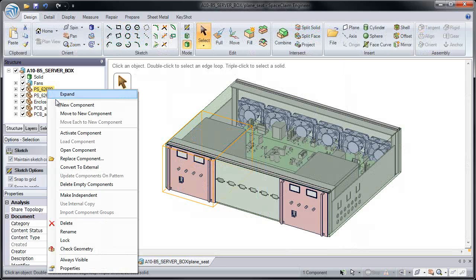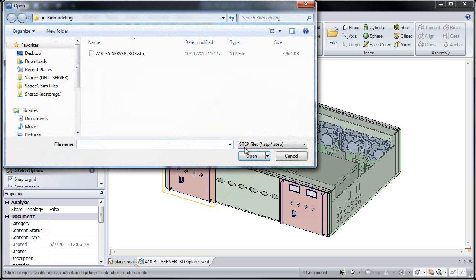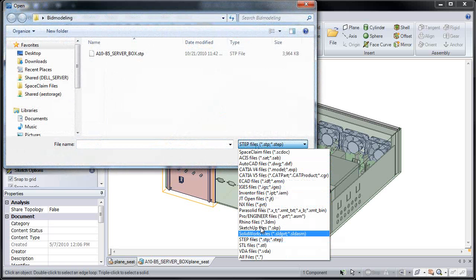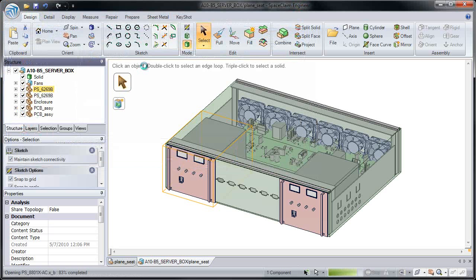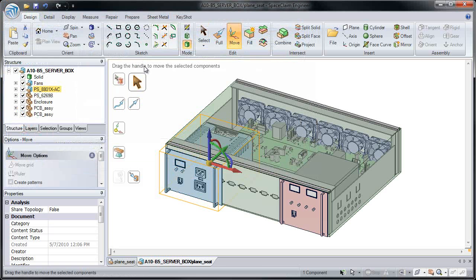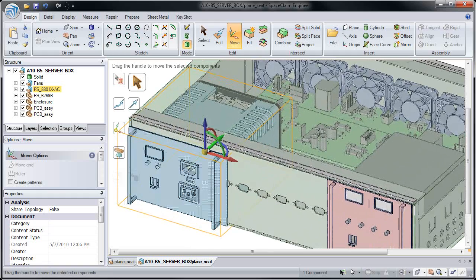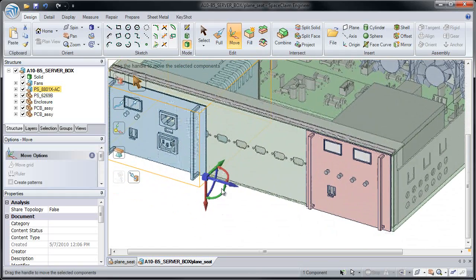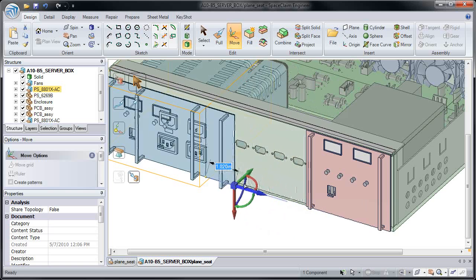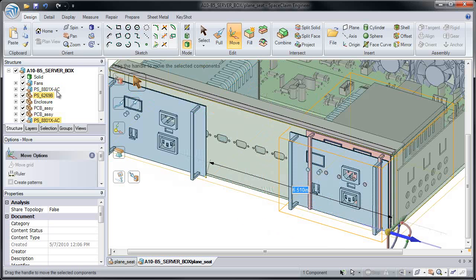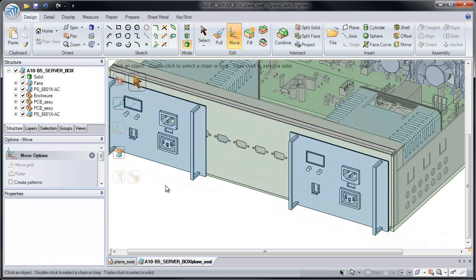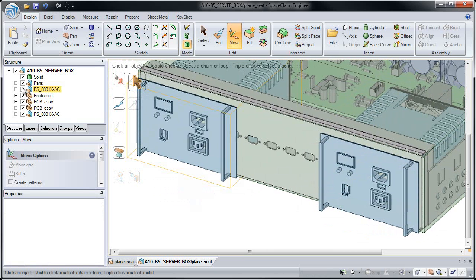After sending out some of the dimensions to our vendors, a lot of times they'll send back a 3D model. Here I'll bring in a Parasolid file and replace our old one with the new one, and it snaps right into place. SpaceClaim easily lets you work with your designs, make copies, and snap them into place. Now we have two of the new designs in our model.